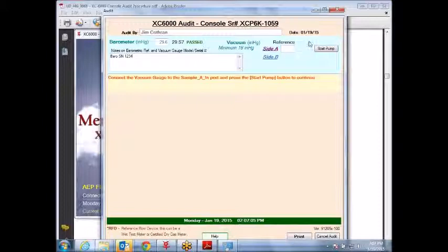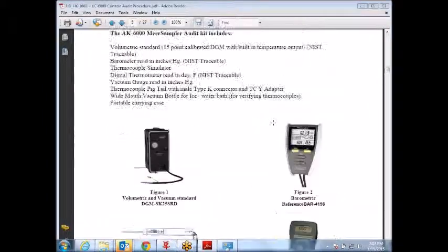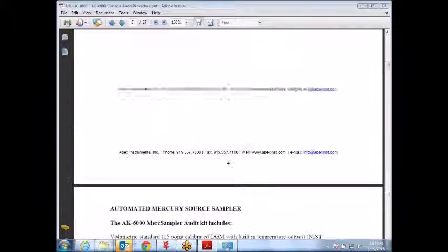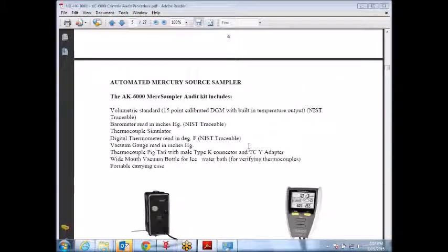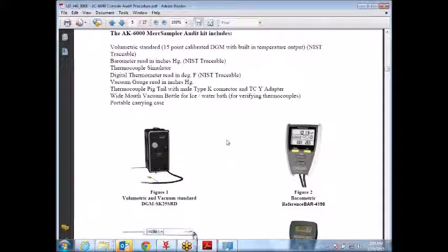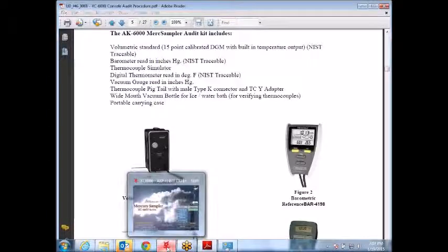So what I'm going to do is, or Dave's going to do it for me. He's going to hook up my audit kit. If you look at the front of the audit kit right here, you notice there's a vacuum gauge on it, and here there's a knob, and basically it'll shut off the flow. So I'm hooking up the audit kit to the A inlet port. Then when I turn my pump on, I will shut the valve, and then I'm going to read what the vacuum is on this. This becomes my reference. Okay? All right, so let me go back to my application.